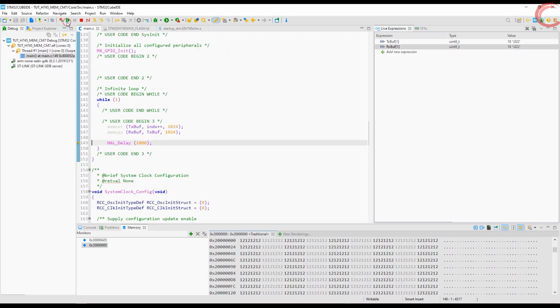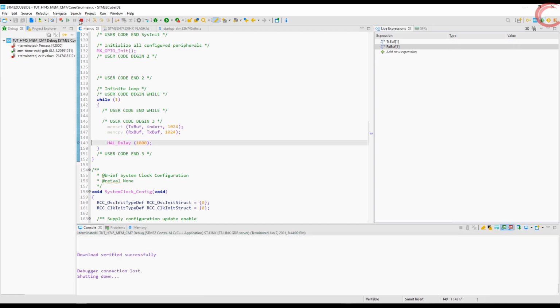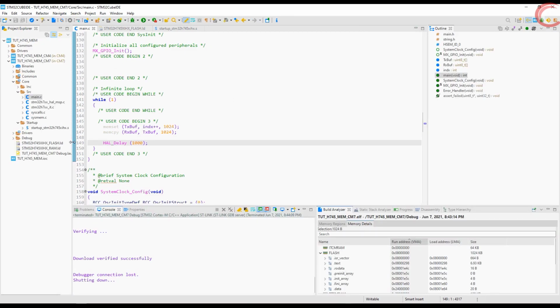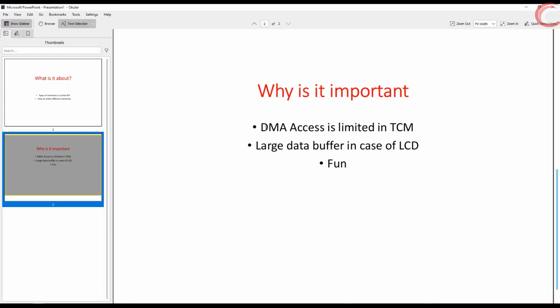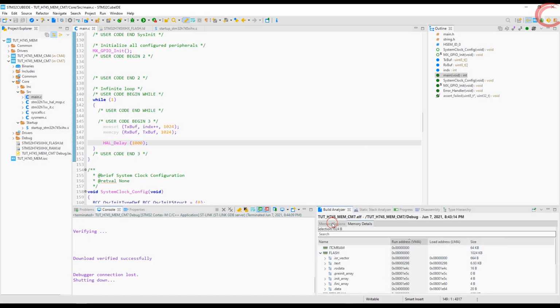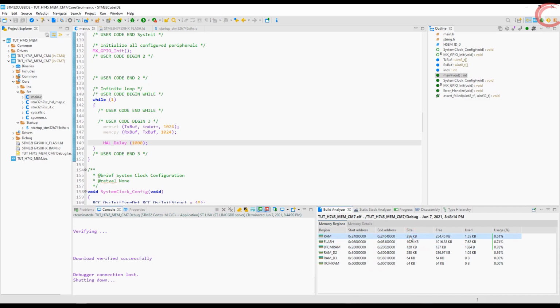Now this is working because CPU can access any memory, so memcopy and memset functions can work on any RAM. But it wouldn't have worked if I try to copy the data using the DMA. I am stressing too much on DMA, and there is a good reason for it. Most of the peripherals, like LCD, SD card, SDRAM, and others will use DMA by default, and that's why we need to be prepared for those conditions, where we simply can't use CPU to copy the data around.